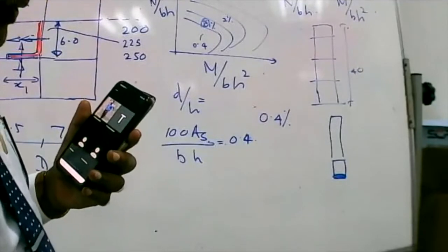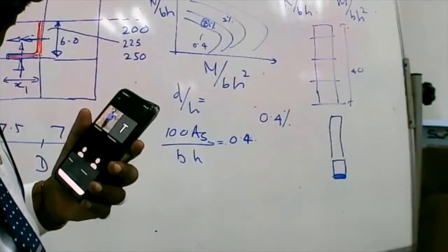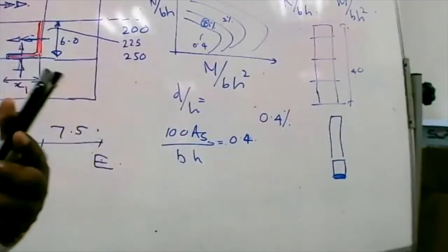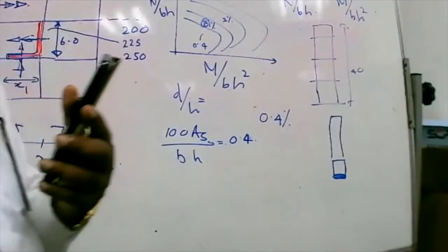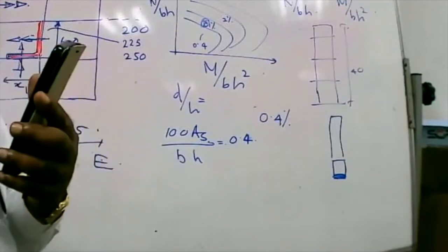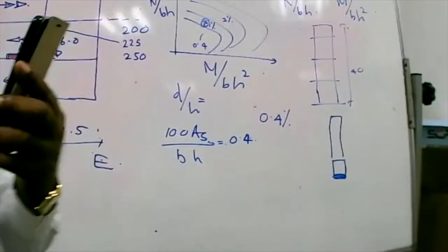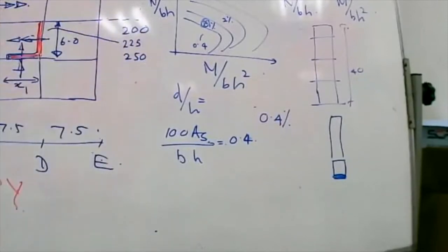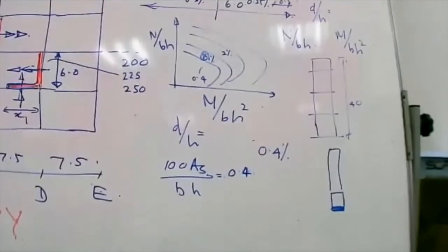Otherwise, you will find that the soil strength is not sufficient. So you may need one basement plus one semi-basement type of situation, provided the water table is sufficiently low. You might go for that kind of solution.